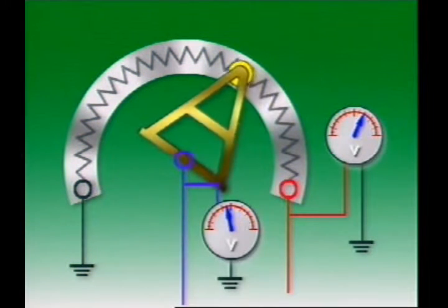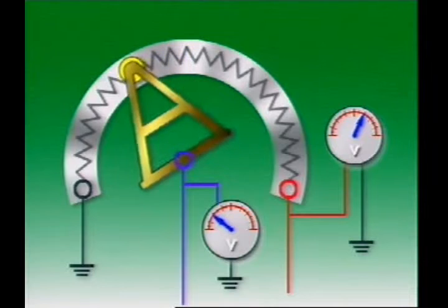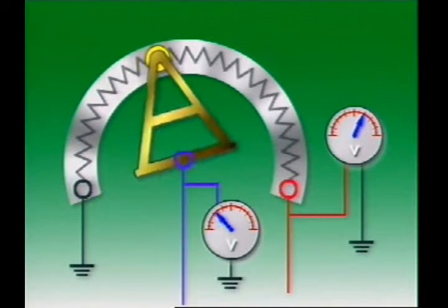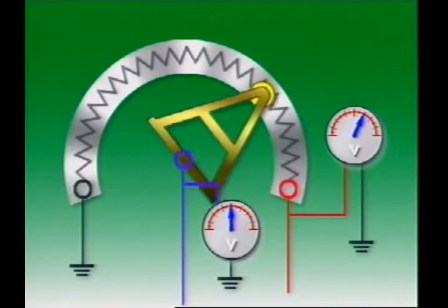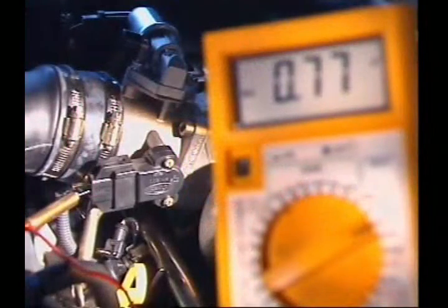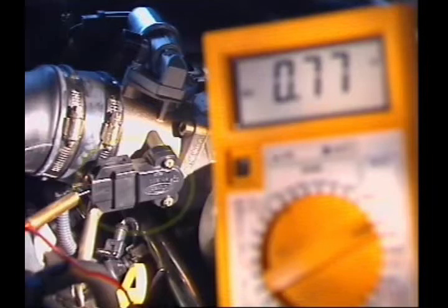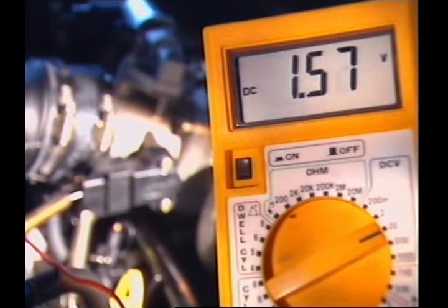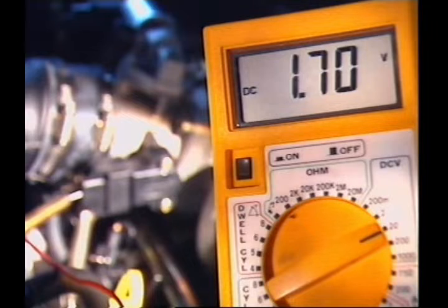As the center sliding contact moves across the resistor, it measures the voltage at the point it is in contact with, and provides a reference voltage for that position. In automotive applications, the circular form is commonly used as a throttle position sensor, with the center contact attached to the throttle plate. The throttle plate position can then be monitored by the control unit.